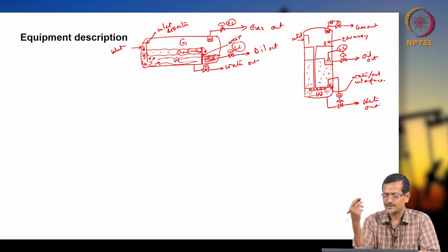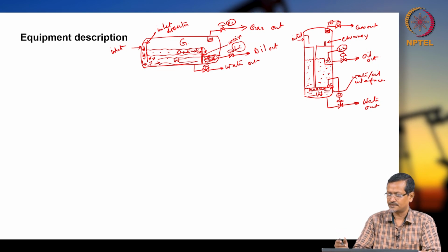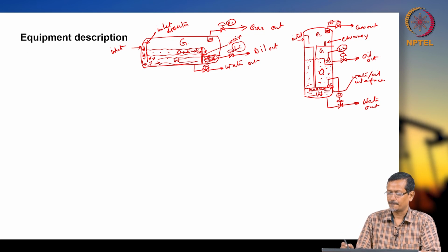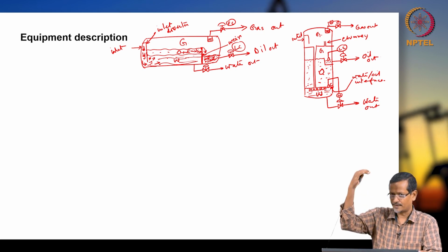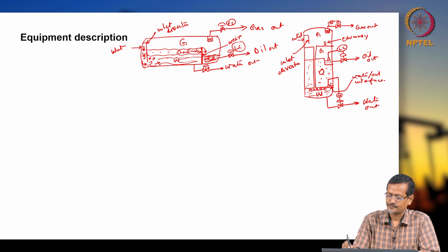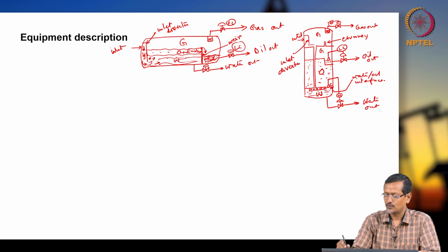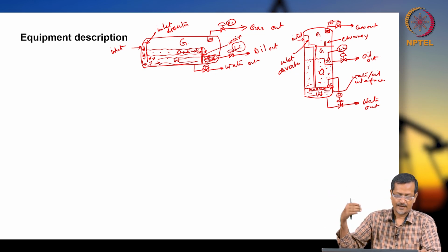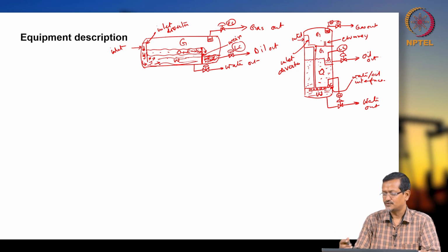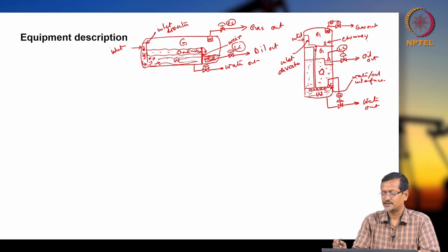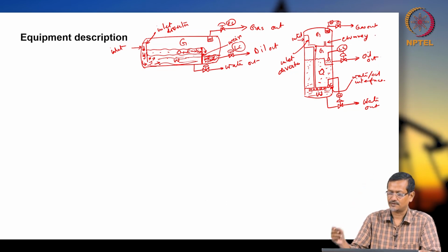Okay, the purpose of the chimney is to equalize the pressure inside this closed area, oil, water, gas. So if any gas is there, it will be equalizing the upper part and lower part. And this is the inlet diverter as usual. Inlet will be diverting, and slowly liquid will be entering here. Okay, free gas will be going out anyway, and if still there is some gas available, then from the water and oil layer it will be bubbling up slowly and going out also, because this gas chimney is there, the equalizing port.